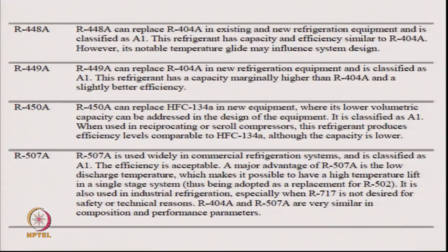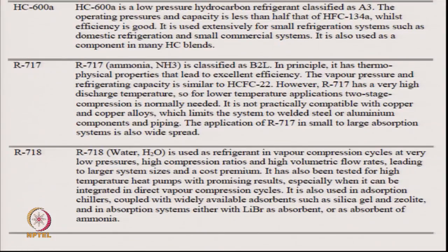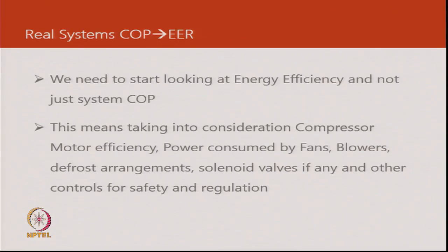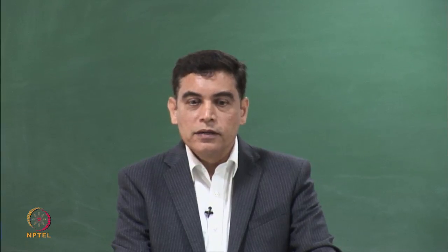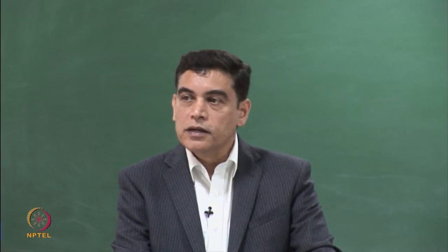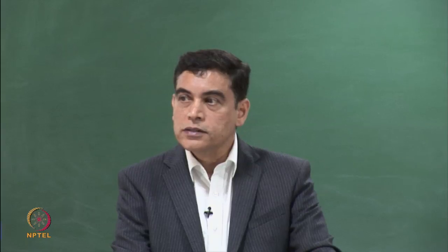So here you can see a full spectrum of refrigerants, and real systems. When we are designing systems, we need to start thinking a little differently. So not COP but energy efficiency ratio. So we saw that we don't have the ideal reverse Carnot cycle in systems.